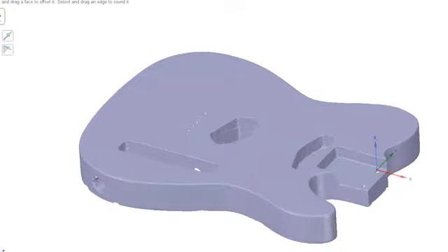Then in this third section, we have the ability to process the point cloud, so you can reduce noise, sample the data, reduce it down to a lower level of information, and then what we call wrapping it, which is converting it into a polygon mesh. And then in this mesh section, we have a repair tool that looks for inconsistencies in the mesh and fixes those automatically.